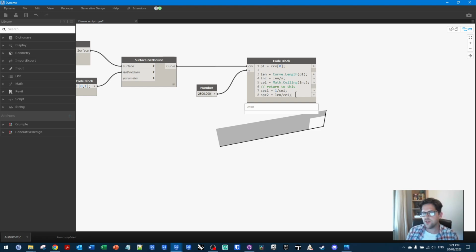And in this case, we actually want to create a sequence of UV parameters to place these points across that curve at, because we effectively want to create a grid of UV points in both directions as close as possible to that. Now we've effectively got our parameter, or our spacing parameter here, which is 0.2, because we have 5 panels across a domain of 0 to 1 of the curve. So we're going to use this in order to create a domain which will let us place points at the center of each panel. So if you can imagine, currently we're going to have points in a sequence that start at the beginning of the curve and end at the end of the curve minus 1 point of domain. So it'll go from 0.2 to 0.8.